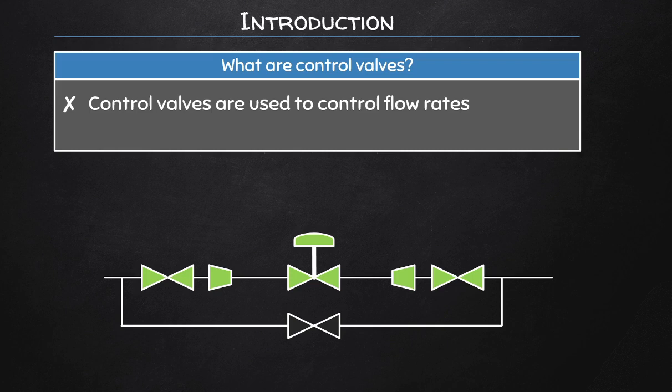Now consider placing a control valve in the delivery line of a pump, for instance. If the control valve is half closed, and you close it further, then the pressure in the line between the pump and the control valve would of course increase accordingly due to the restriction of flow, while the flow out of the control valve would also obviously decrease.